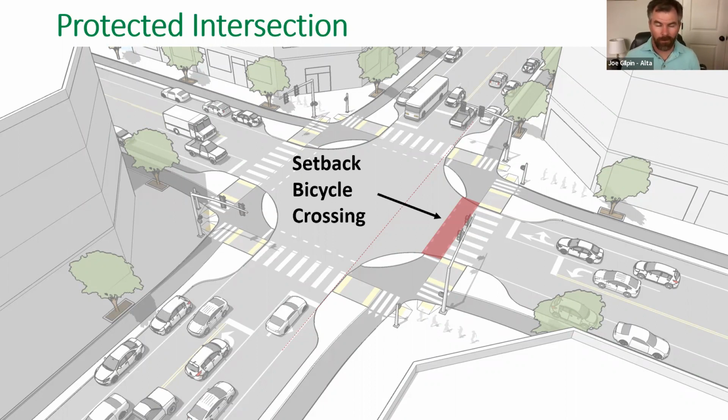So you may fully accommodate all of your motor vehicle traffic, and yet you're still devoting green time to that approach because a pedestrian is still making his or her way across the intersection. So having a more compact intersection will give you greater flexibility in your traffic signal operations, more flexibility in terms of coordination, and to dynamically serve the demand that is approaching from different legs. So there's a lot of benefits that you can get from that.